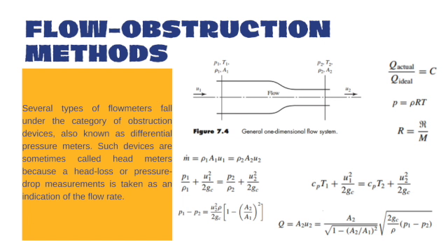However, although we assumed frictionless flow, some losses are always present in the flow. This volumetric flow rate shown here is the ideal value and is usually related to the actual flow rate through an empirical discharge coefficient, followed by the equations that are shown in this chapter.